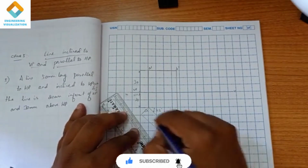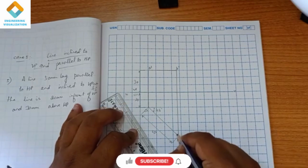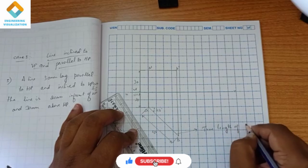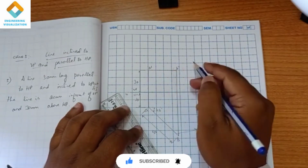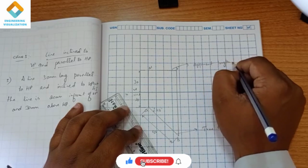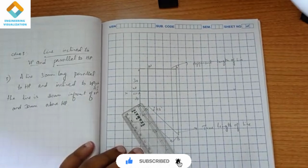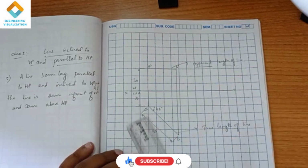It's 50, right? If the length of the line remains the same after projection, we call that the true length of the line. If the length of the line is reduced after projection, we call that the apparent length of the line. So true length of line means the length remains the same after projection, and if it gets reduced after projection, it is the apparent length of line. So this completes the problem.